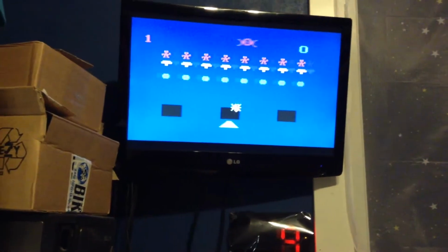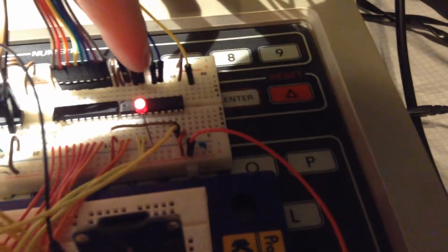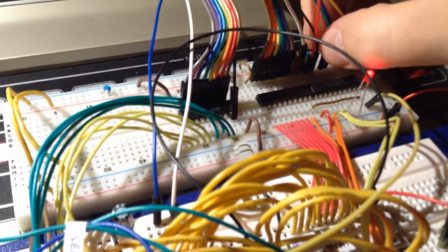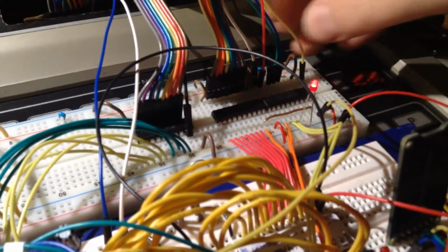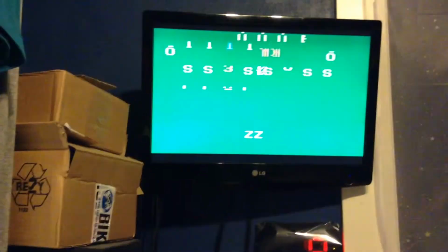Okay, so let's talk memory map. Now we have it running. I haven't done anything to the image file, so even though I haven't done that, I can do a reset, I can press 1 and it starts. So what I've done, I have removed A10 from here and I moved the black one over here. So now we have a working system. However, if I move everything back which it's supposed to be, you can hear now the computer crashed, do a reset, it's no longer working.